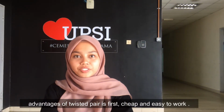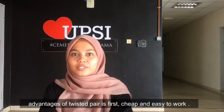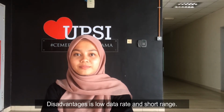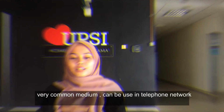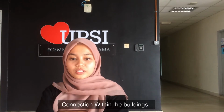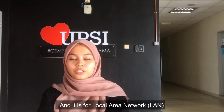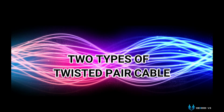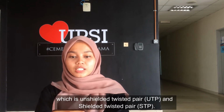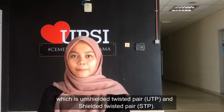Advantages: first, it is cheap. Second, it is easy to work with. Disadvantages are low data rate and short range. It is a very common medium, used in telephone networks, connections within buildings, and for local area networks. Twisted pair cable has two types, which are unshielded twisted pair (UTP) and shielded twisted pair (STP).